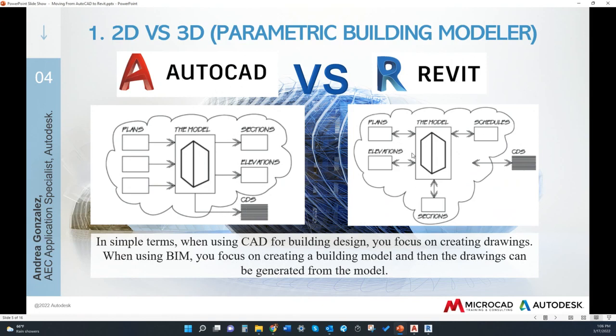And in BIM with Revit, the design process revolves around the model. Plans, elevations, and sections are simply 2D versions of the 3D model, while schedules are reports of the information stored in the model. A change made in one view automatically will update call-out tags and sync with the sheet numbers. This is called bidirectional associativity.